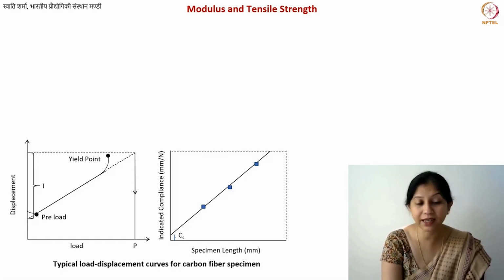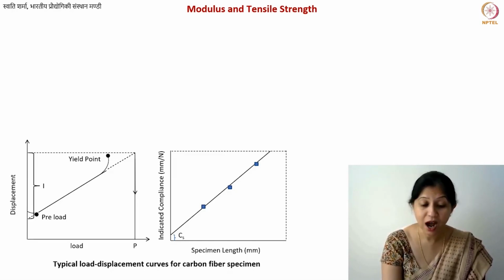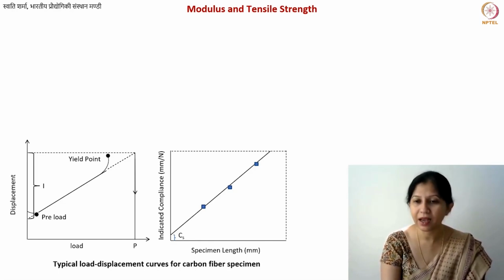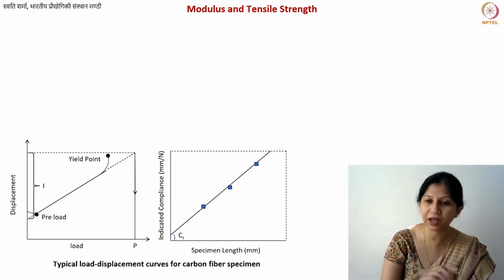This is always the case. You get strain hardening in the case of viscoelastic polymers as well, that we had learned before. What happens is carbon fibers are not like polymer fibers. They do not have the same kind of geometry or microstructure. However, they do have these long sheet and chain like structures. So they do tend to at some point align themselves, and therefore you may get a little bit of strain hardening, but typically even that is not very significant.